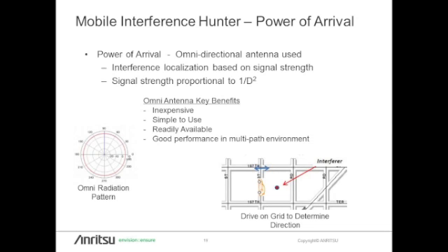And so you're driving there. Well, yes, you measure, say, minus 60 dBm signal strength, but if that's the only information you have, the interferer could be on the left, or for that matter, if you're just starting there, it could be on the bottom or the top, or where that street where the driver is. So you really don't know the direction. You just know the power level, with that one measurement.